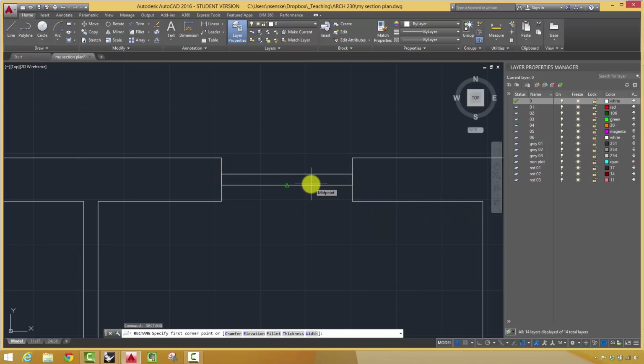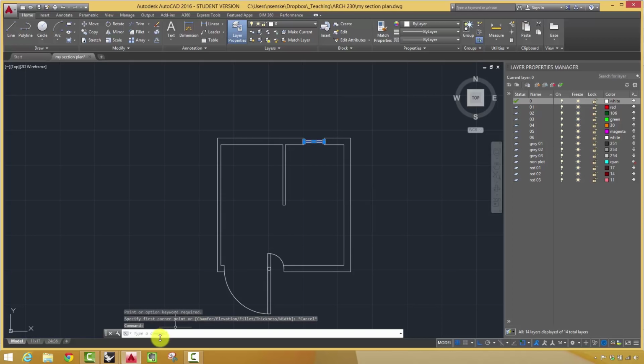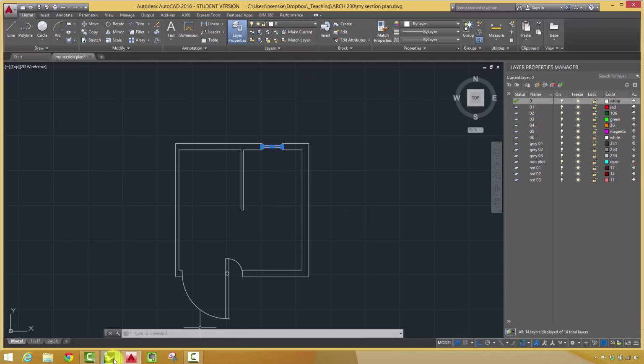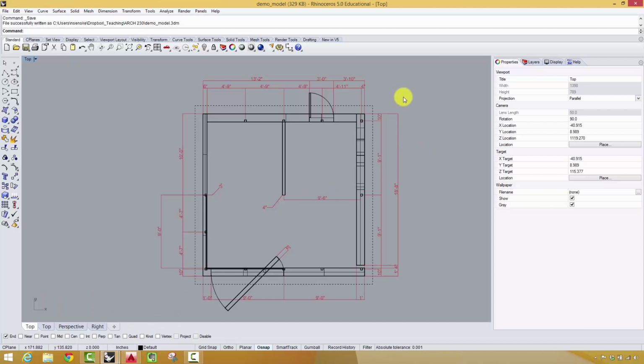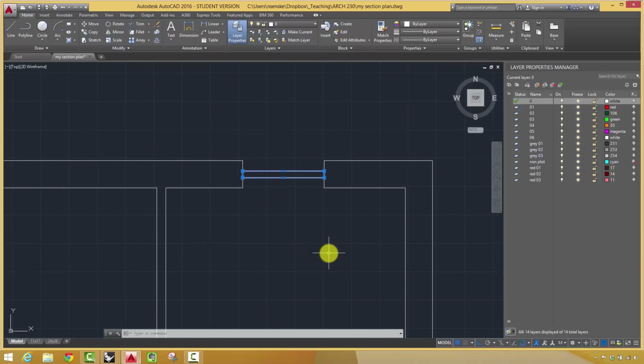And you want doors typically to swing out for safety's sake, because if people are getting out in a fire, you want them to swing out. You can swing in if it's definitely an entry door, but in this case, I'm going to have it swing out. I want people to come in this way, because I want this wall to be in the way, so I want to swing it out in that direction. You gotta be kind of thoughtful about this.